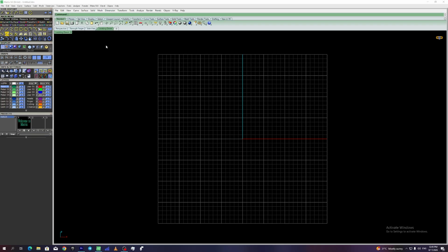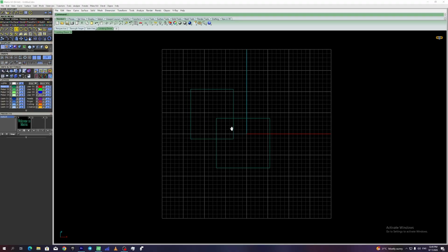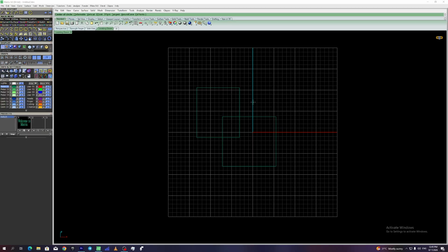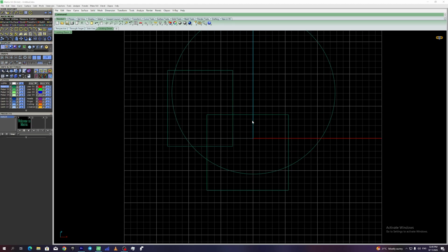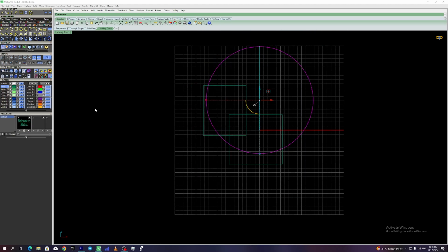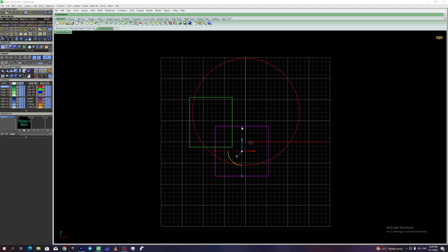And pro tips for you: explode before rebuilding sharp cornered objects. Join only works when endpoints touch. Closed shapes need at least 2 split points. Use the command bar undo for quick fixes. These commands are absolute game changers. They give you the power to break, reshape, divide, and refine your designs with incredible precision.